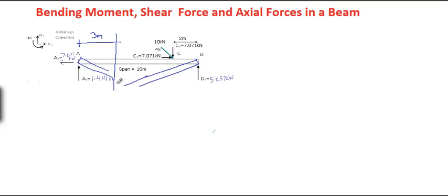So this indicates that there must be some forces in the beam at this point to resist collapse and keep the beam in equilibrium. If we apply the correct internal actions, which are shear, moment and axial force, to the cut face, the free body diagram should be held in equilibrium again, and we can use the equations of equilibrium to work out the internal actions at the cut.